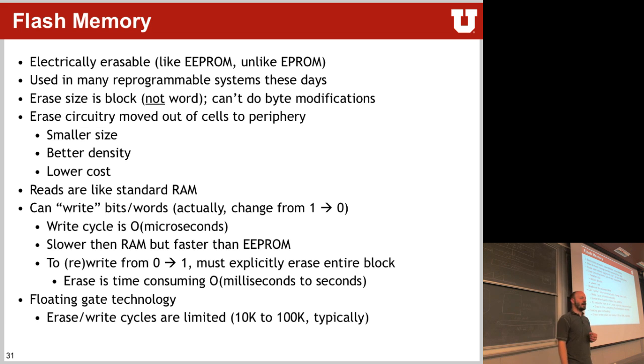The technology is what's called a floating gate technology, and unfortunately, you can only have about 10 to 100K erases. So flash memory is not a very good memory if you have to write and read from it all the time. If you have USB sticks, better make backups because they're prone to break eventually, especially if you run, for example, Libero on top of it or use it as a live file system to read and write from all the time. And they do break eventually.